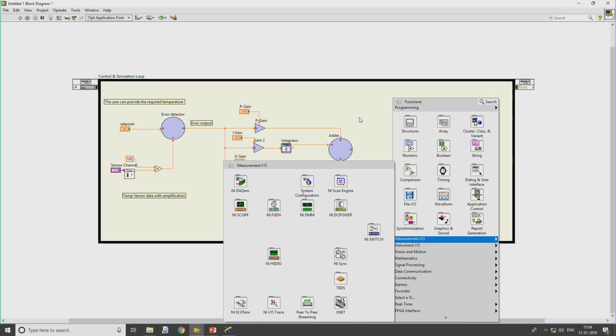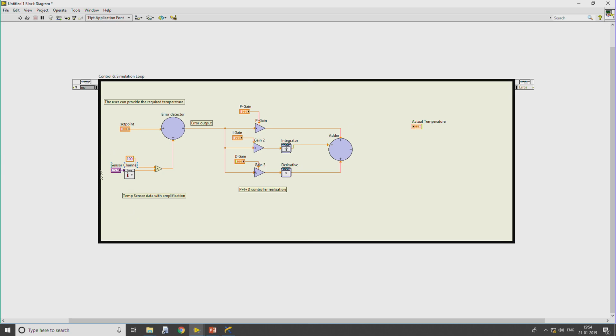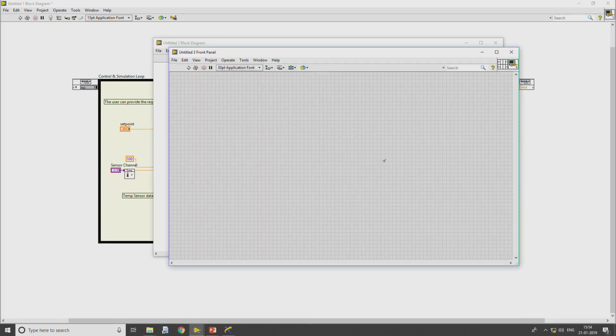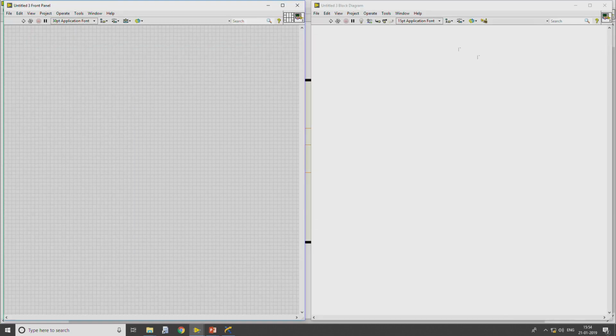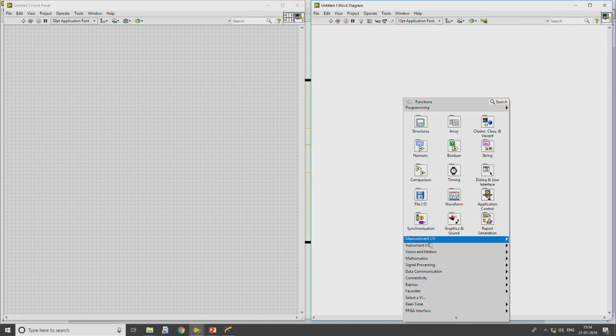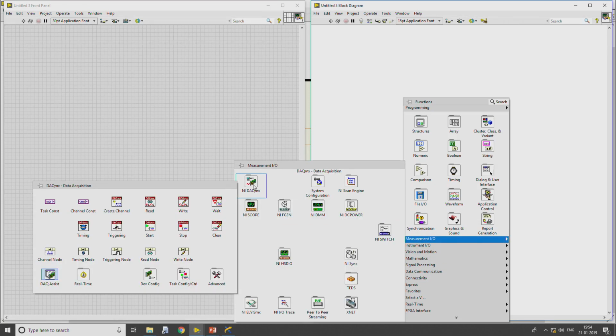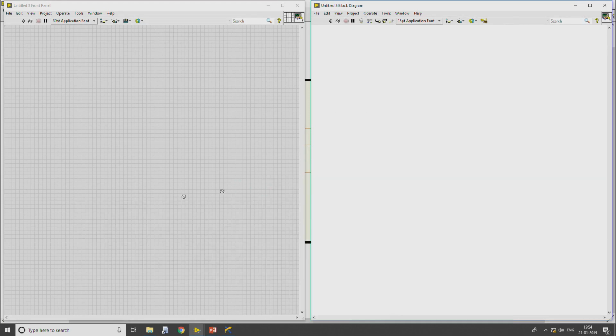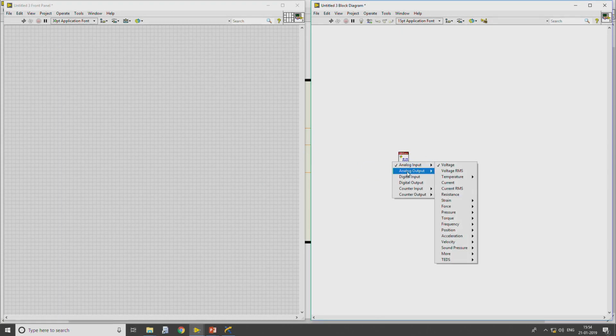So, which is similar to what we have created for acquiring the signal from the sensor. In order to do that, I will create another LabVIEW file, containing the data about from which particular channel the manipulated variable has to be given to the real world.